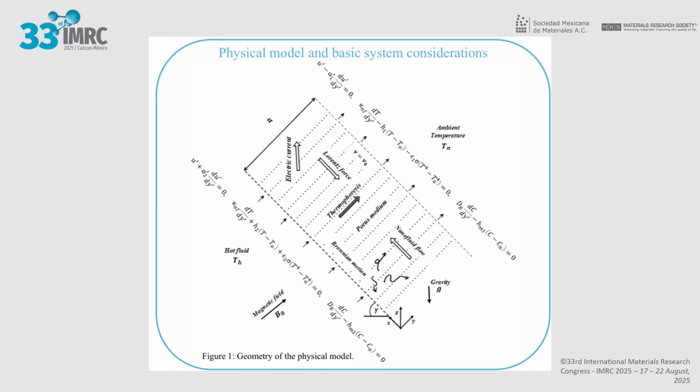The nanofluid is injected uniformly through the bottom wall, while suction occurs through the upper wall. Hydrodynamic slip conditions are imposed on both plates, enabling a more realistic representation of interfacial effects in microscale systems or surfaces with low roughness. The thermal analysis includes the effect of nonlinear thermal radiation modeled using the Rosseland approximation, as well as terms associated with viscous dissipation and ohmic heating, resulting from an interaction between the magnetic field and conductive fluid.